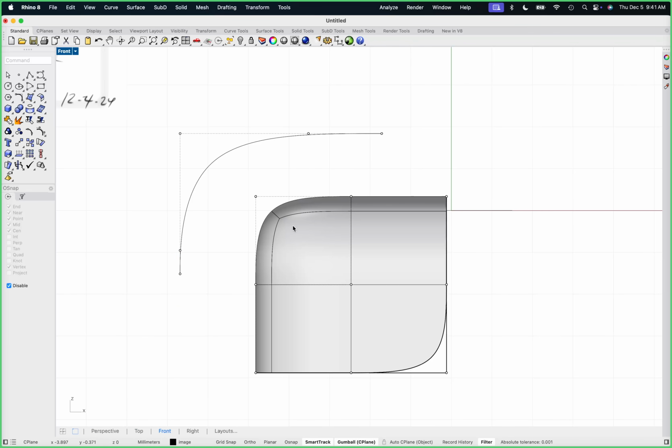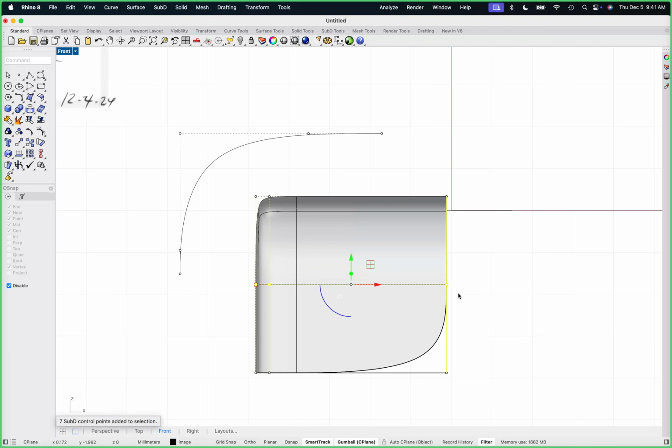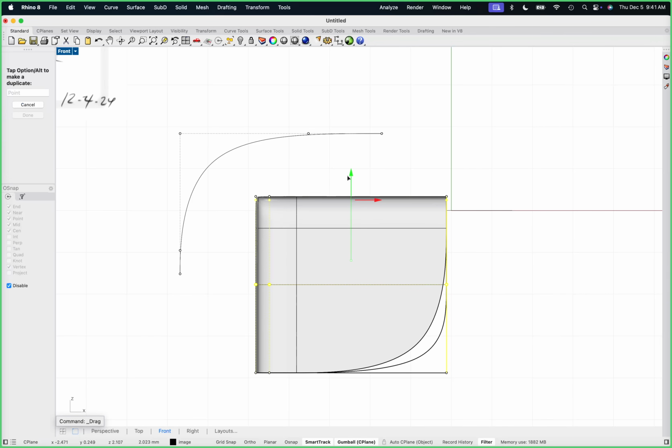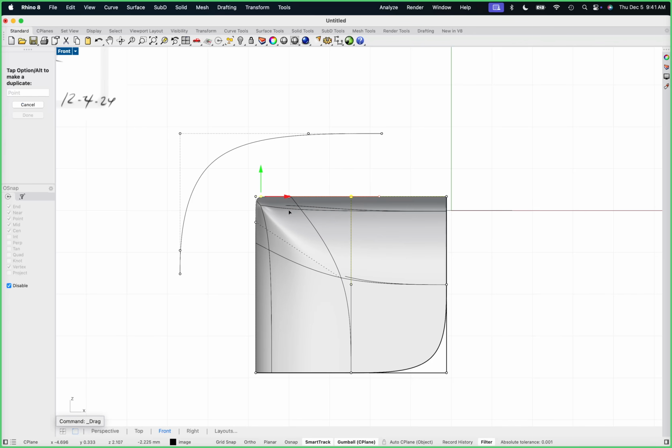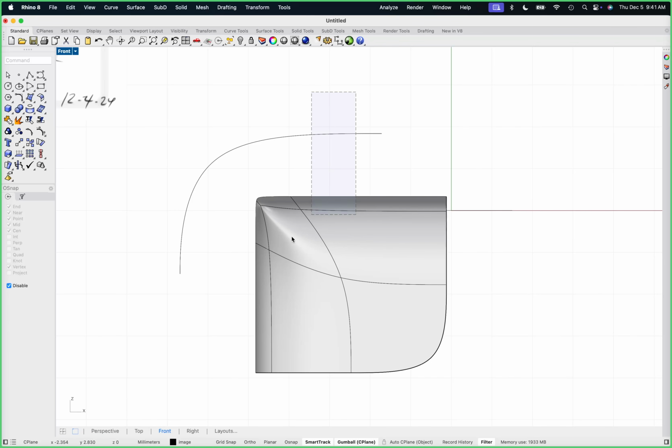Right? 1, 2, 3, anchor. Anchor, 1, 2, 3. If we want the SubD edge to get sharper, we move these 2 points or these 2 edges together. Okay, now the fun part about SubD is I can just move this point and make just that corner sharper, right? And leave these alone, right? That's how the transitions work. But the goal is to keep this stuff super light.